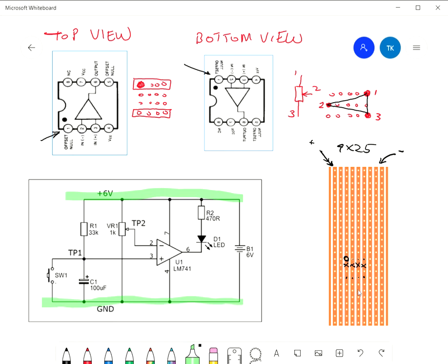And we'll leave one row blank so that we have a bit of space, and then we'll use this hole there to connect the LED. So it's pin 6, and we've got an LED there, and we're going to connect it to this row there. Now if you look, this strip of copper has no other connections, so we're using this to connect our LED.